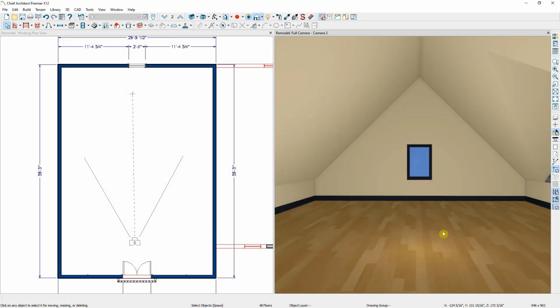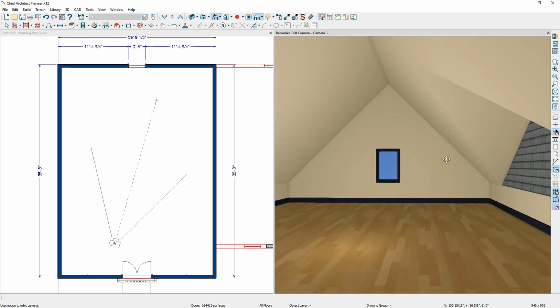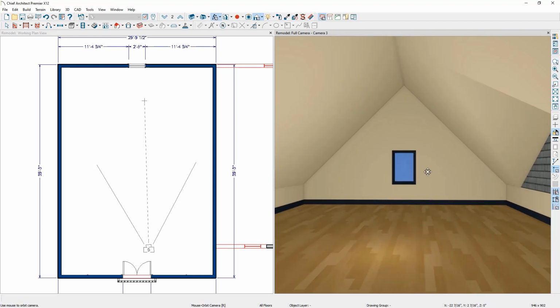And so there you can see how our walls are building shorter, and we've dropped our ceiling and roof quite a bit. You'll notice on the right hand side there that our existing roof structure is butting into this room, and we'll clean this up here in a little bit. And so next we have a couple more ceiling design options available for this bonus room. You could have the bonus room just vault how it is and go to a peak, or you could have it coming up and then be a flat ceiling again.